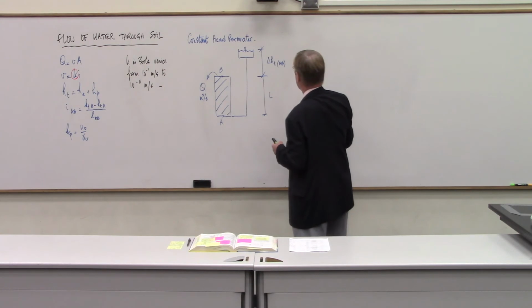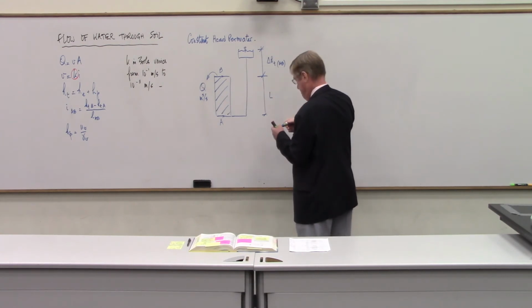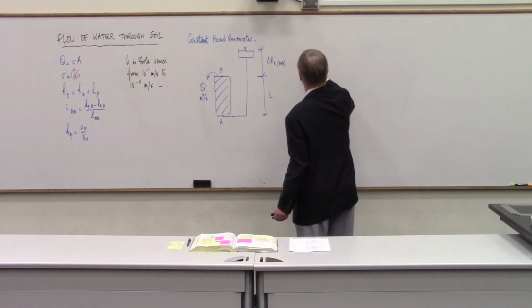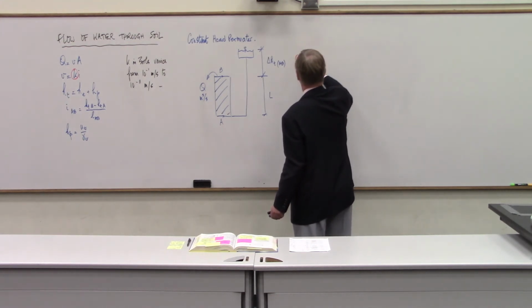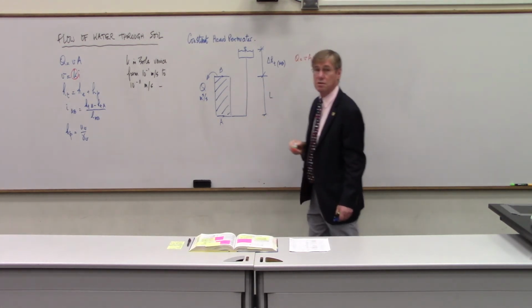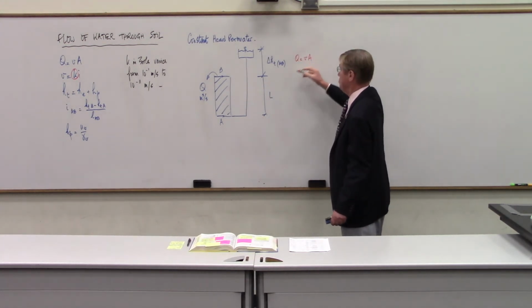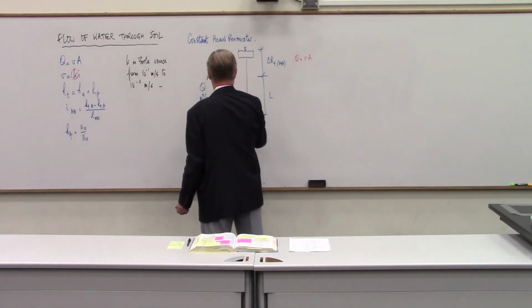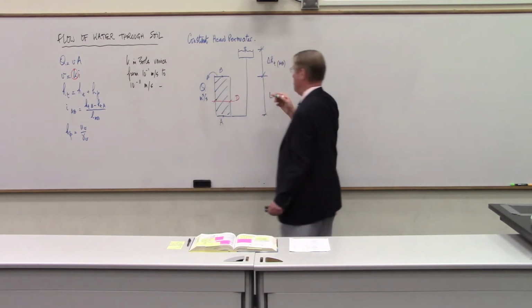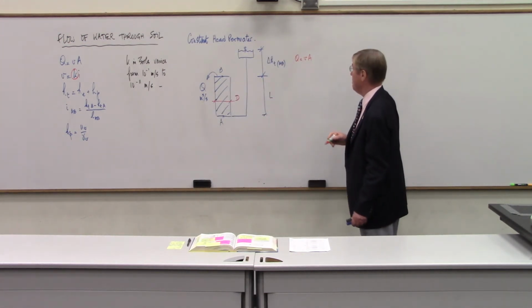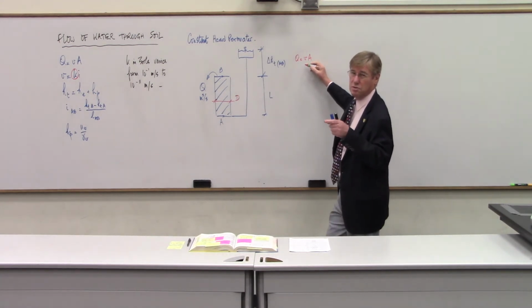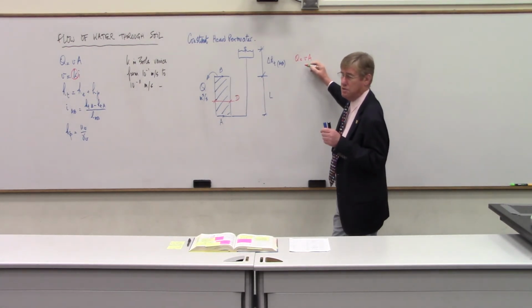So if you write the equations that you have, and that is Q equals VA, A being the cross-section of the sample. Let's say that the sample has a diameter D, A would be pi D squared over 4, and V would be the discharge velocity. Remember the distinction between seepage velocity and discharge velocity?